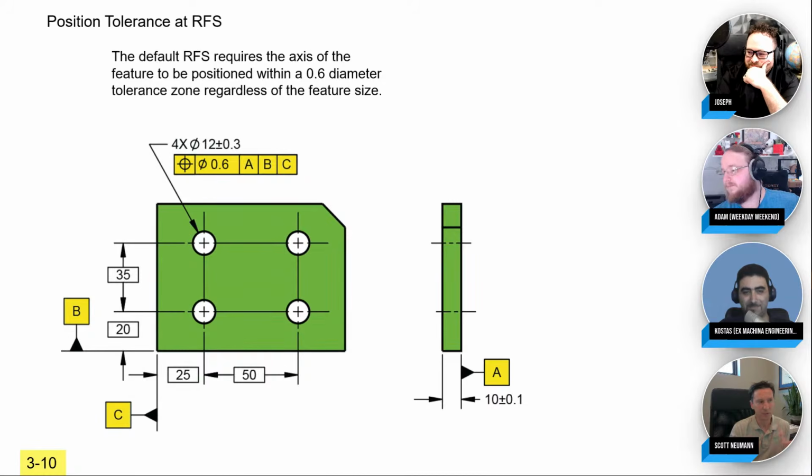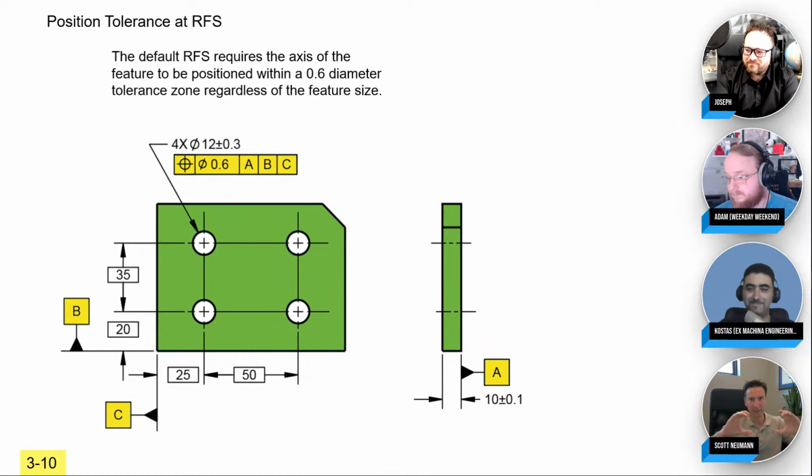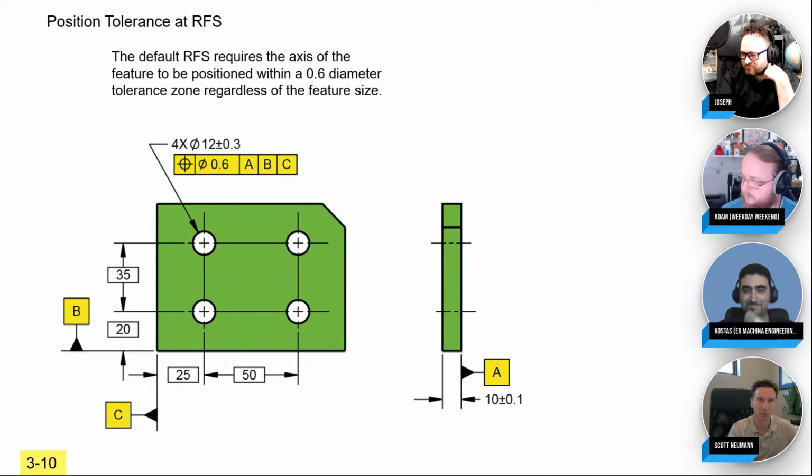I think plus minus works really well for temperature and pressure and voltage. It's too much, too little. That's all you could ever have. When you have a 3-dimensional part with holes that can vary, perpendicularities and position tolerances in different directions, plus minus tolerancing didn't really work very well. So geometric tolerancing is a new tolerancing language for interchangeability on 3D variations.